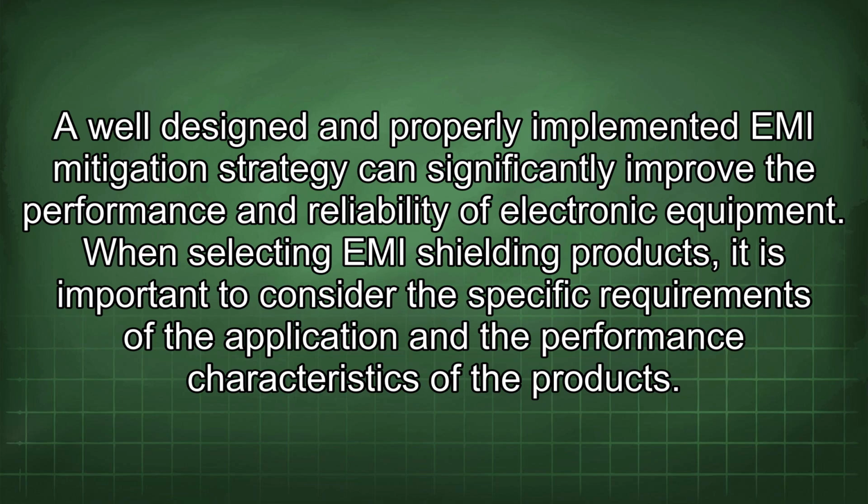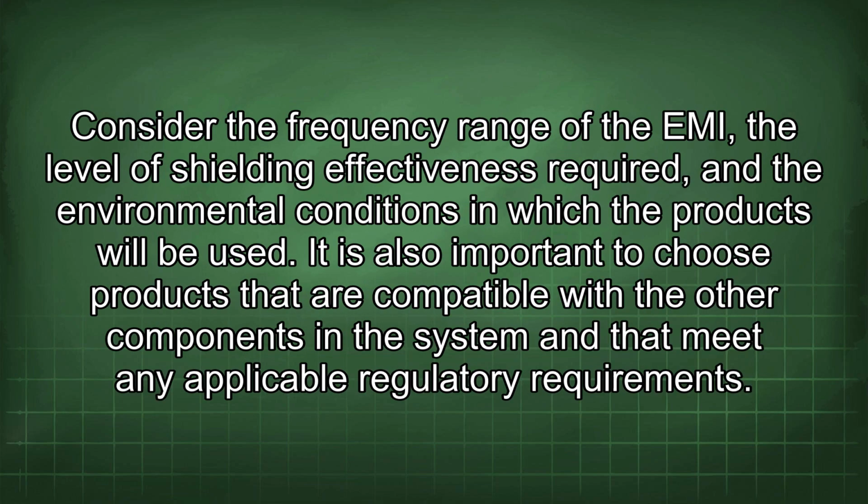When selecting EMI shielding products, it is important to consider the specific requirements of the application and the performance characteristics of the product. Consider the frequency range of the EMI, the level of shielding effectiveness required, and the environmental conditions in which the products will be used. It is also important to choose products that are compatible with the other components in the system and that meet